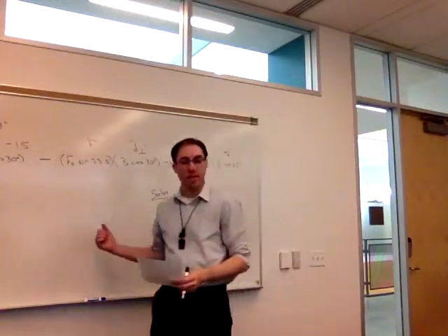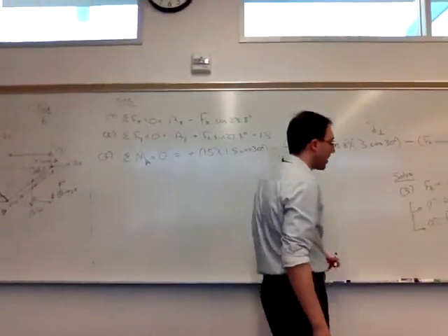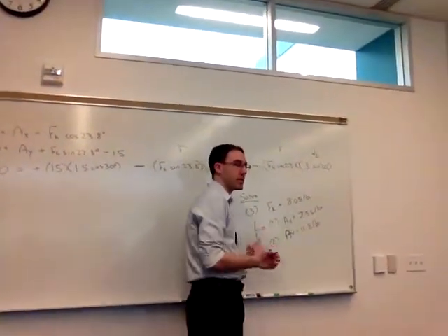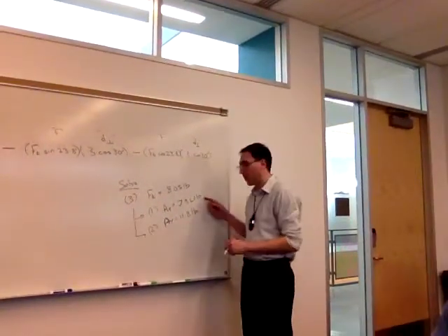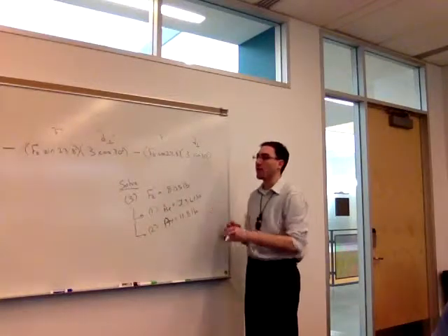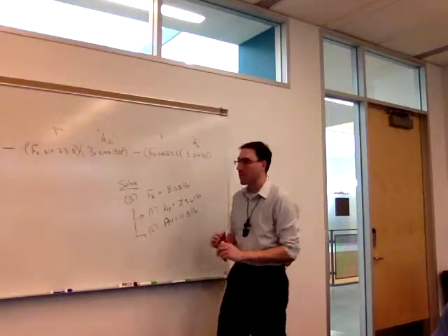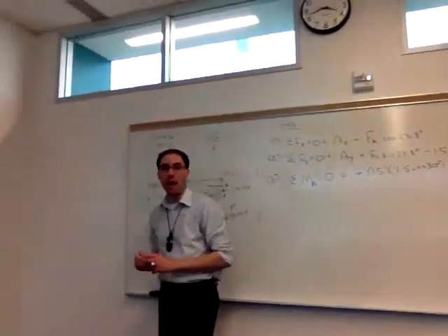It's actually going to turn out we don't need Ax and Ay, but we don't necessarily know that at this point. There's no harm in solving them. It might just be by hand, it's just a little bit more work. And in real life, we probably would be interested in what these pin reactions are. For the problem, though, the only thing we need to find is K, which we'll see when we write our fourth equation, has nothing to do with Ax and Ay.